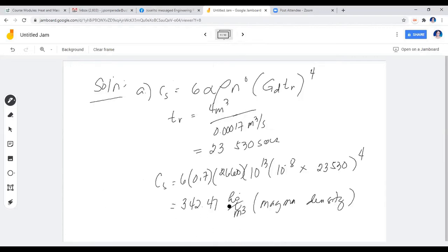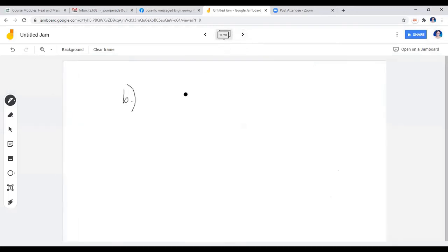If our production rate should be in mass per unit time, and this one is density, kilogram per cubic meter, then we will use the given production rate in cubic meter per second to get a production rate in mass per unit time. Just like any production rate we speak of in chemical engineering or in production, that has a unit of mass per unit time.